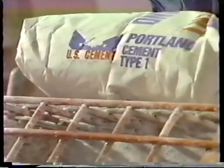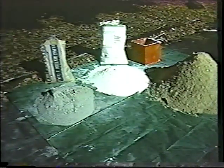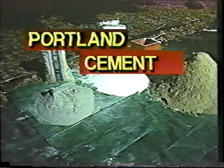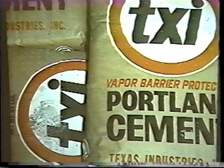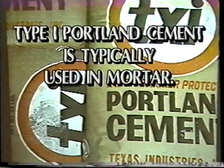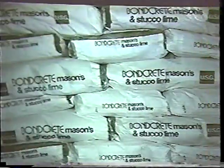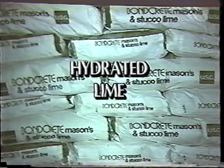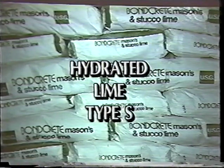The ingredient which provides bond and gives the mortar strength is the cement. Two types of cement are used in mortar: Portland cement and masonry cement. Portland cement is used in combination with hydrated lime and sand. Type I Portland cement is typically used in mortar. Hydrated lime is used with Portland cement to make the mortar more workable. Mortar requires Type S hydrated lime.